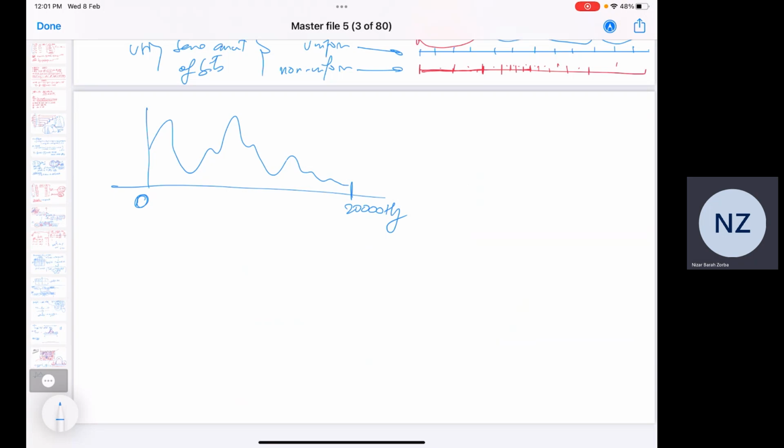Okay, if you take your signal, you start talking on the oscilloscope with the mic, this will be your voice signal, okay? You shout, you do whatever, okay? Your voice is squeaky, very bassy, okay? So here it will be like this. Clear? Whenever they would like to send the signal, they said that everything from 100 hertz to 4,000 hertz is actually what is important. All stuff here is not that important. They have analyzed the signal. This is why our mobile phones, whenever they send, only send from this part to this part, and all of this is neglected. It is not even transmitted.